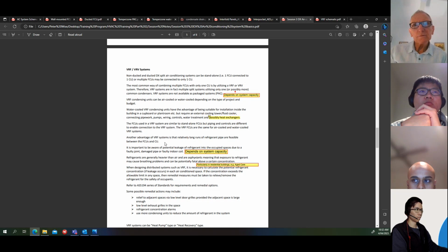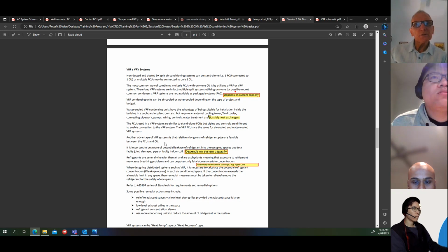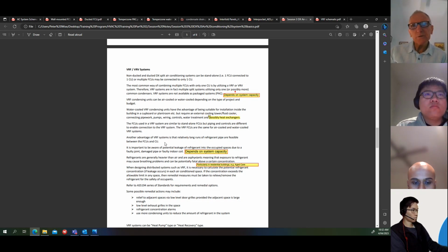So that person, unfortunately, may not wake up because they can't breathe. The refrigerant replaces the air in the room. So this is an issue that you need to be aware of and you need to deal with when you have a distributed system.